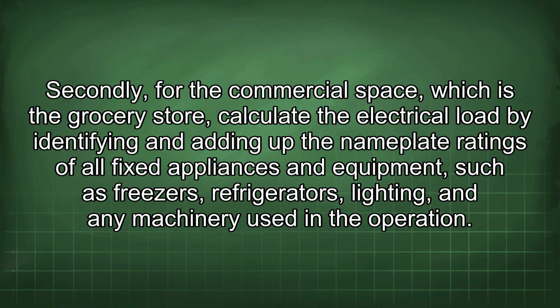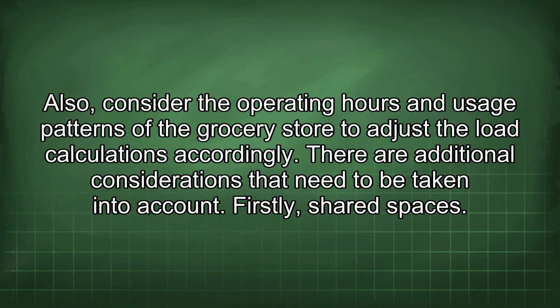Secondly, for the commercial space, which is the grocery store, calculate the electrical load by identifying and adding up the nameplate ratings of all fixed appliances and equipment, such as freezers, refrigerators, lighting, and any machinery used in the operation. Also, consider the operating hours and usage patterns of the grocery store to adjust the load calculations accordingly.